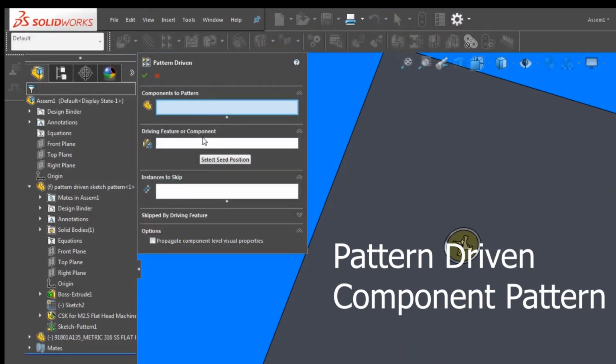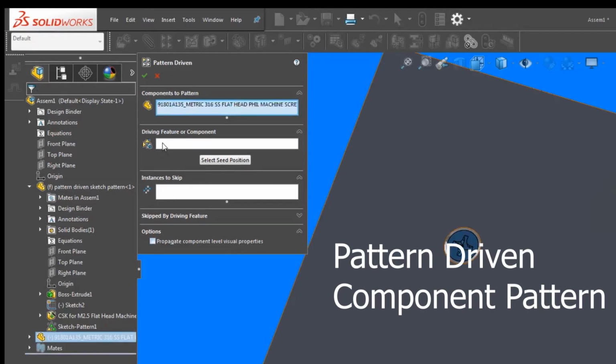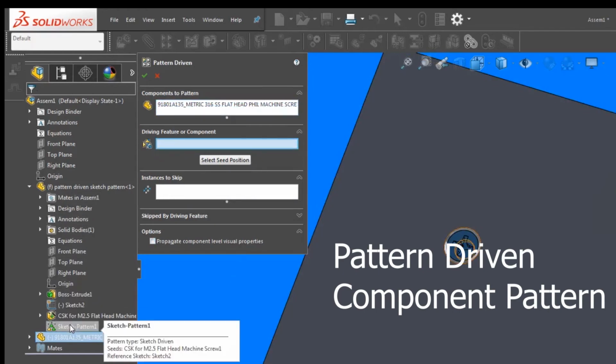Under Components to Pattern, select the screw, and under Driving Feature, we will go to the assembly tree and select the sketch-driven pattern created in the plate.